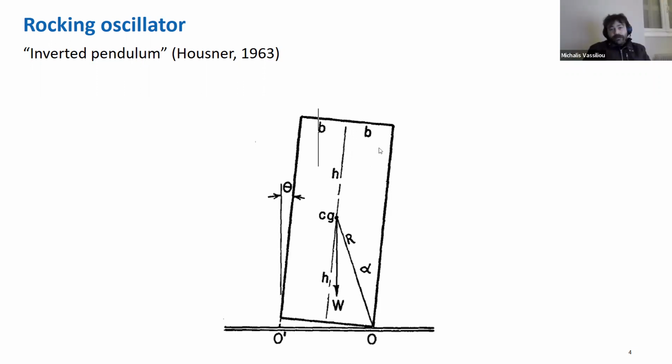So if the frame is equivalent to a column of larger size, then the frame is more stable than the columns, because we said that something larger is more stable than something smaller. So I add weight on top in the form of a beam, and I increase its stability. And the Parthenon, the fact that it's stable. This is counterintuitive, because usually top-heavy structures overturn more easily, like an SUV overturns more easily than a Formula One. But in rocking, this doesn't hold. Okay, wow, this is really nice.